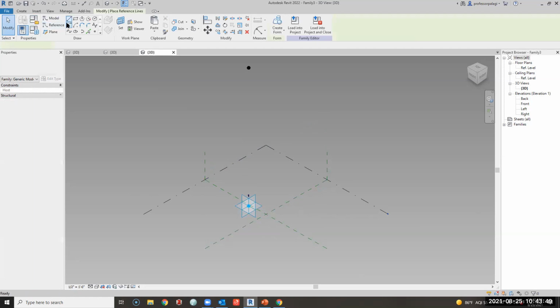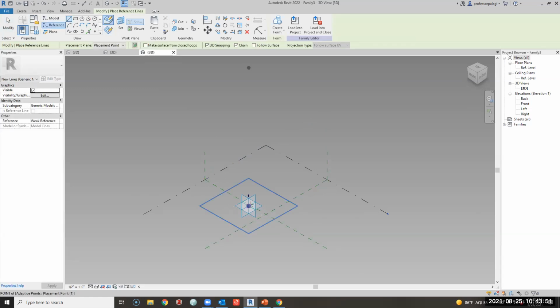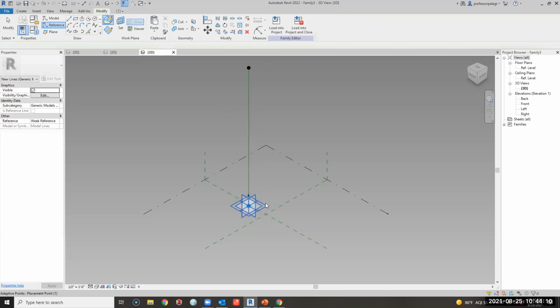Now I'm going to go reference line from that point. This is where the 3D snap is really important, because if that 3D snap's not on, it'll look like you snapped to it, but you didn't. You'll orbit around, you realize it didn't, or it moves, and all of a sudden the line stays there and the other stuff moves, right? So this is the whole thing, this idea of hosting: one thing telling the next thing what to do is important. So snap there, escape again.